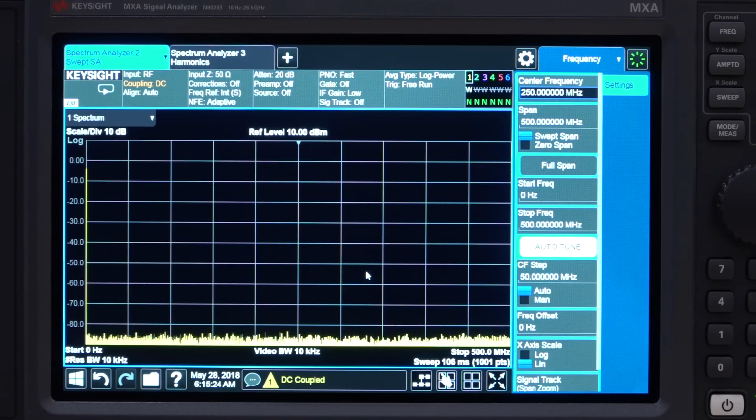Now, before we do some wireless experiments, let's take a look and see the linearity of the instrument under various conditions. So I want to see what kind of linearity and intermodulation products I can get if I were to use this to generate multiple tones for wireless system characterization. So here I'm going to generate a 10 megahertz signal just as a starting point, a basic sinusoid. Here it is. Here's our 10 megahertz signal.